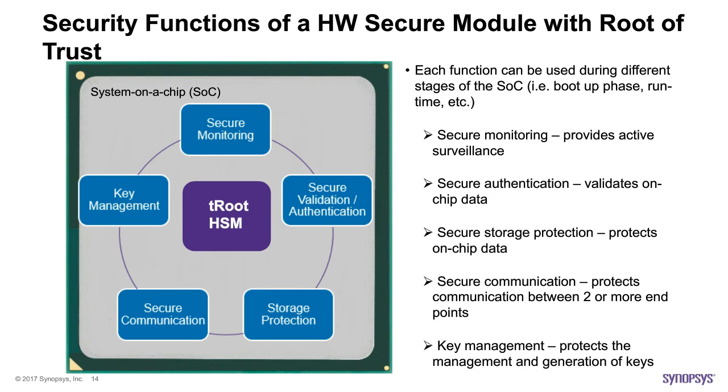Secure validation and authentication. This feature is responsible for ensuring the validity of the code and the data on the SoC. The evaluation of the integrity of the code and data can be done through an authentication scheme, such as an RSA or ECC signature check. Typically, you can expect this operation during the power-up or runtime stage.